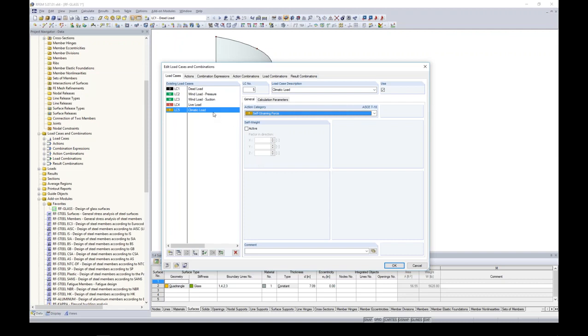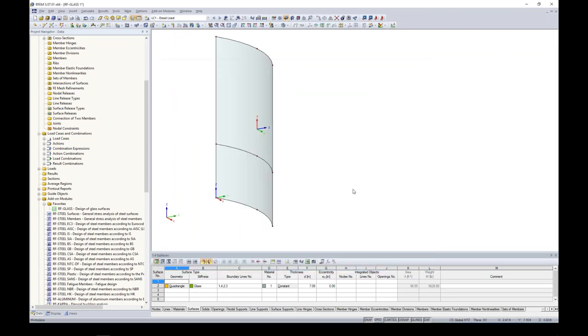You certainly can put your climatic loads into any one of these load cases that you want, but keep in mind, maybe climatic loads you want a load factor of 1.0. When you put it in with dead load, well, now it has the same load factors as dead load. So most likely you're going to want to keep them separate from these other action categories, which is why I created climatic load. This does have a load factor in our ASCE load combinations of 1.0.